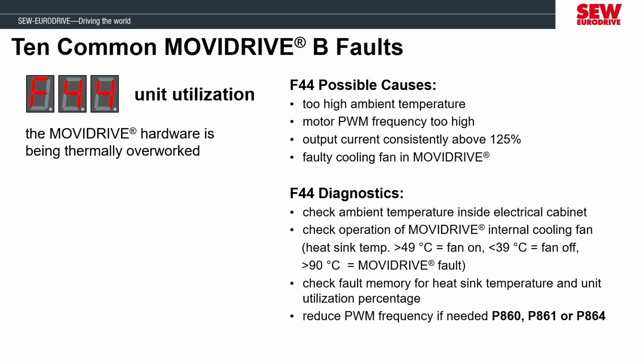If the F44 fault is persistent, then you can check the ambient temperature around the MOVIDRIVE or the operation of the internal cooling fan. An easy way to determine if the cooling fan on the MOVIDRIVE is operating is to lay a piece of tissue paper on top of the control head. It should be blowing if the fan is switched on.